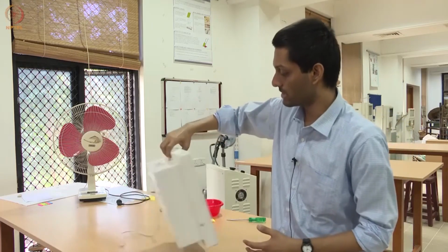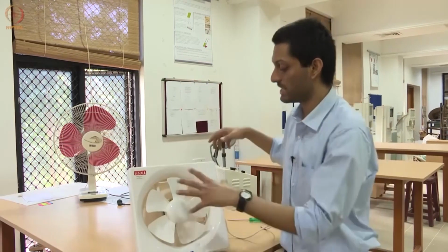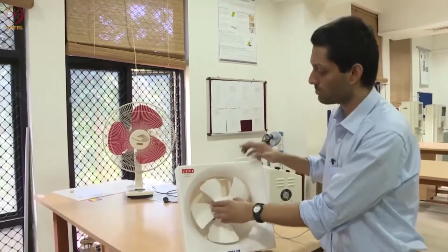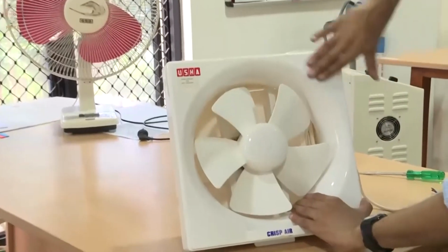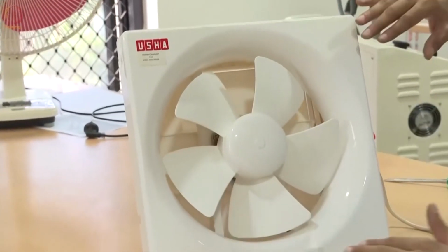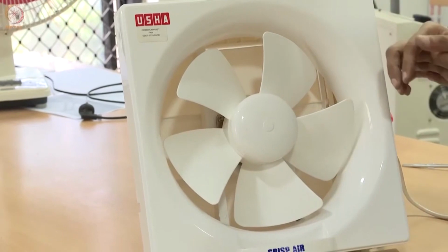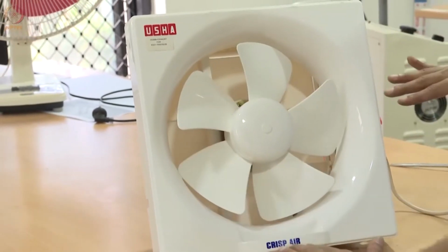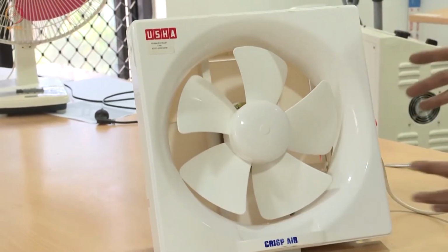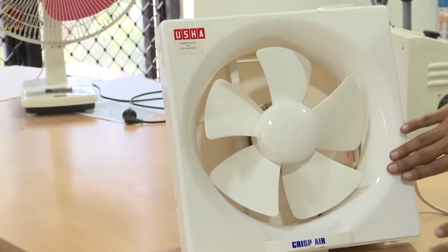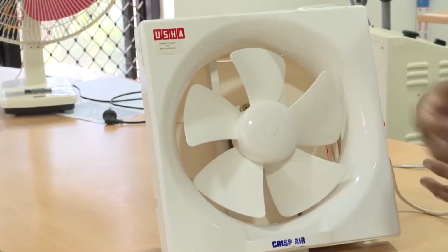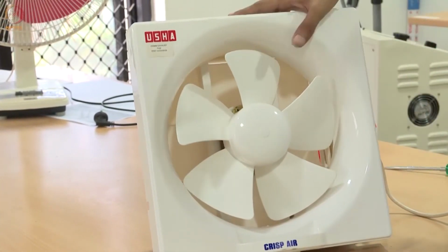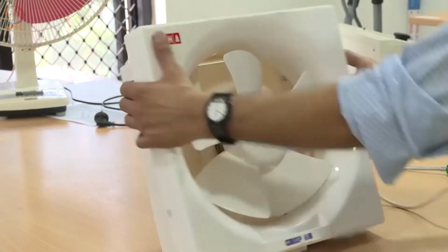So first, let us look at the overall design of the fan. Basically, this is the intake of the fan. You can look at the blade design. This is the inlet, and then you have a diffuser. This improves the efficiency of the fan. The diffuser guides the air into the fan. This is also called a bell housing. Typically you might have seen in aeroplane engine intakes such surfaces that improve the efficiency.